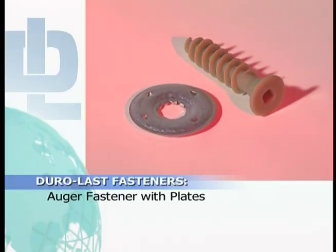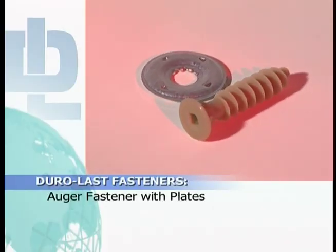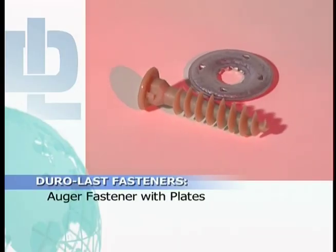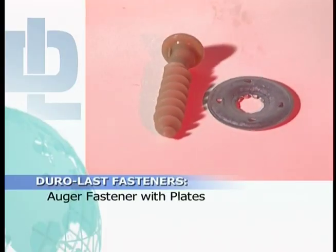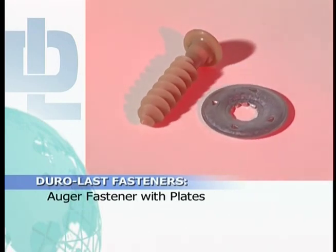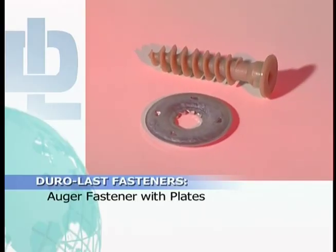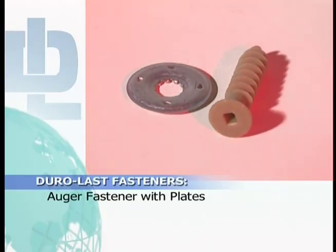A specially designed plate and fastener combination is manufactured with one-way tabs on the underside of the fastener head that lock into the ratchet teeth of the 2-inch metal plate. Gypsum or lightweight concrete decks require a pre-drilled 7/16 to 9/16 pilot hole at least 2 inches deep for this fastener. Do not use a pilot hole when using this fastener on a tectum deck.